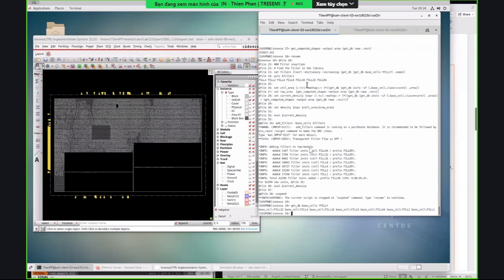So Innovus doesn't matter. With Innovus you can put in any order. It's going to look at the big cell and try to do the big cell first, right? That's usually the case that most people want. So you want to fill the big hole with the big cell first, and then just no more, and then you go to the next cell, right?